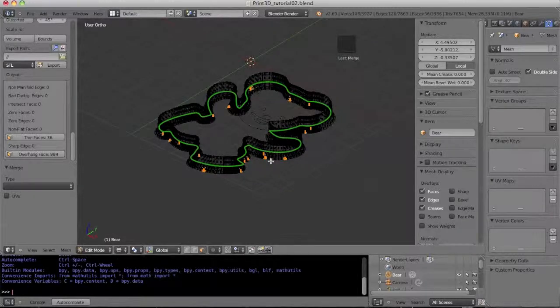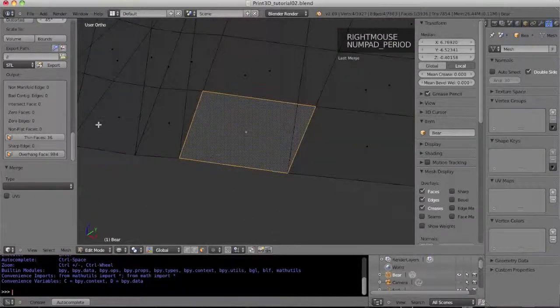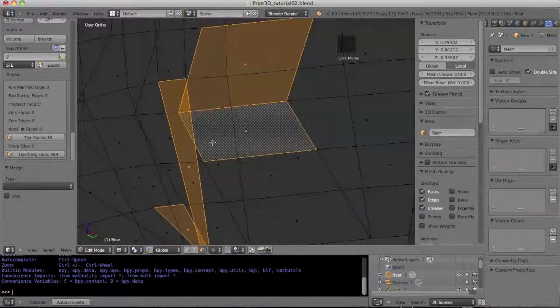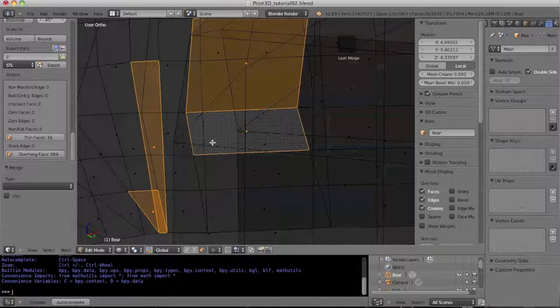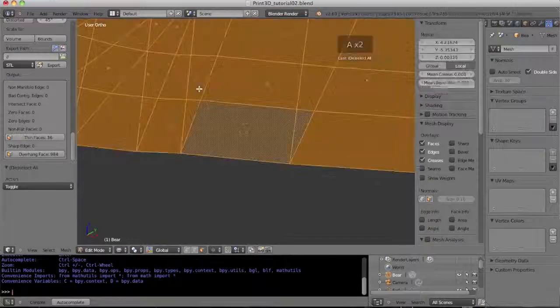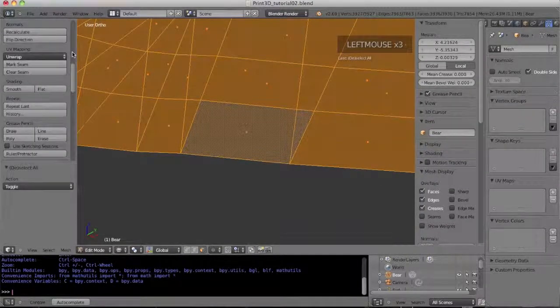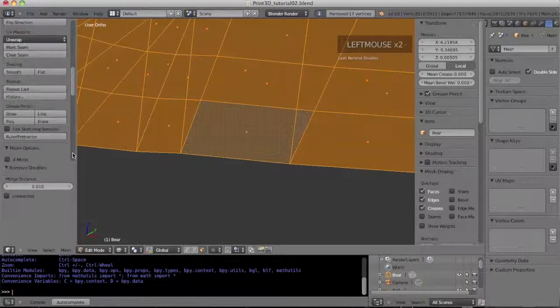I'm not 100% sure whether this is not a problem of the tool itself. So if I select thin faces again, you see here it's somewhat related to those. So not really sure here, but what we could do as well, we could give the overall mesh a try to see whether there are duplicate nodes. So let me remove doubles, and actually there have been doubles.